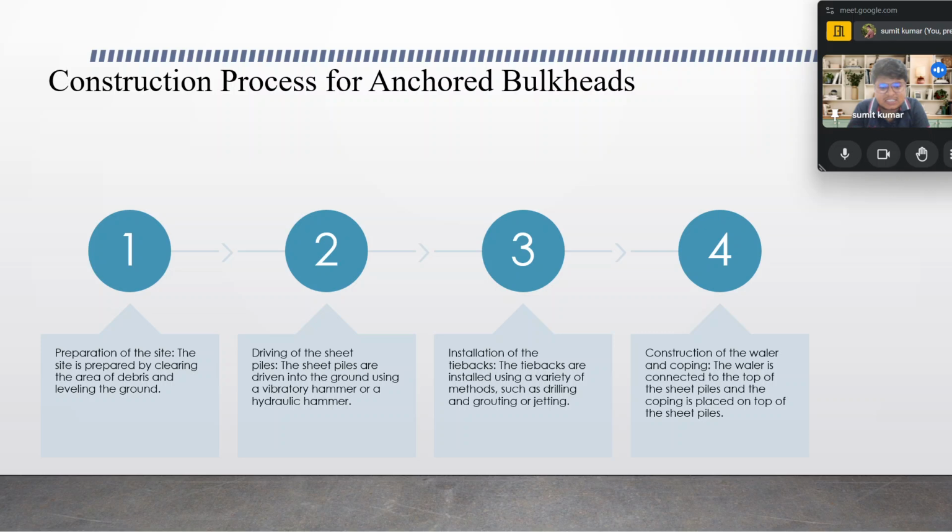Okay, the third one is the installation of the tiebacks. The tiebacks are installed using a variety of methods such as drilling and grouting or jetting. And as we go ahead, the construction of waler and coping. The waler is connected on the top of the sheet piles, as we already said, it is used to connect the sheet piles, and the coping is placed on the top of the sheet piles as well.